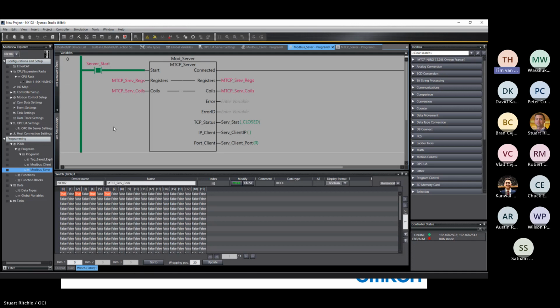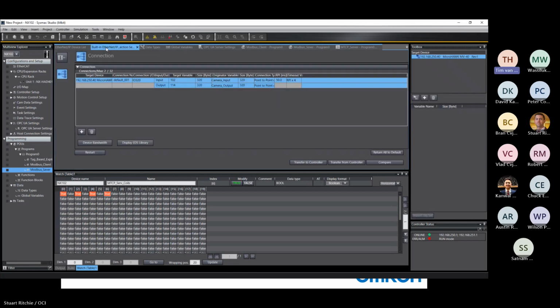Okay. So we're trying to figure out how to set up EtherNet/IP implicit messaging between the two PLCs, and one is outside of that router and one is inside. So basically you have to go through a firewall or whatever. So is there a way to do that? Or is that basically something you'd manage with Layer 3 IP translations on ports?